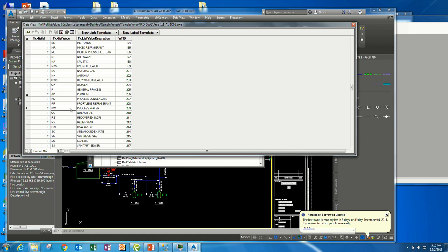So if you do that, and let's say somebody's working the drawing, it won't update anything that's already been selected, but when you go to select it in the future, that modification will be there. Will they have to run sync styles to see that change? I don't believe it's a sync, but it couldn't hurt to run sync styles.